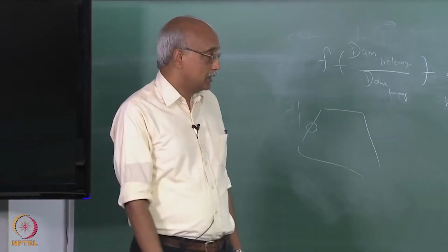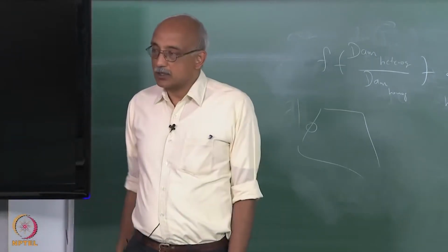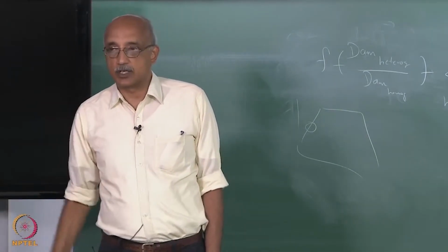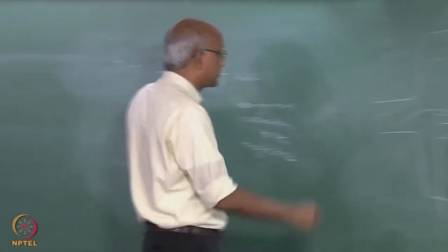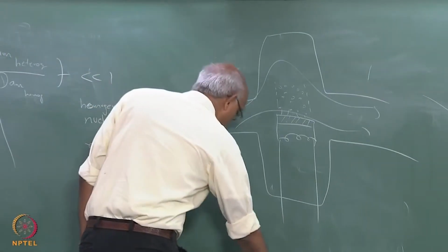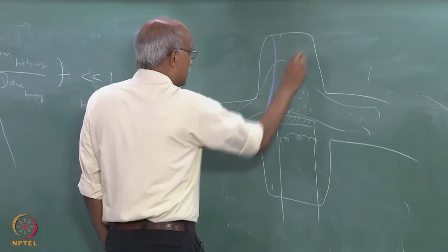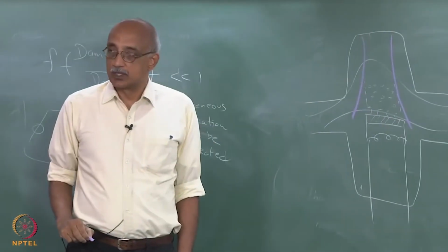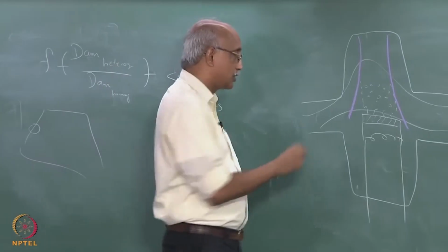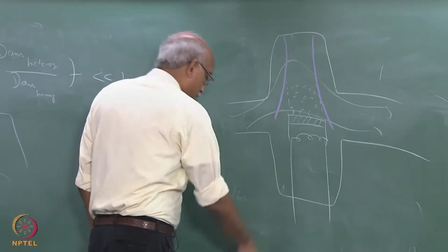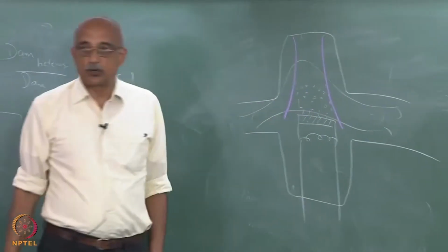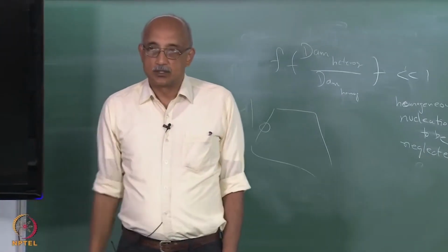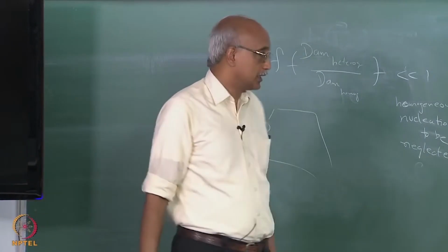So, in fact, more than 99% of aerosol CVD reactors use the stagnation flow configuration. So, instead of this type of driving mechanism, you essentially use a flow field that looks like this. Then the nucleated aerosols are naturally confined to this flow region, right. So, they are essentially driven to the substrate and made to deposit there.